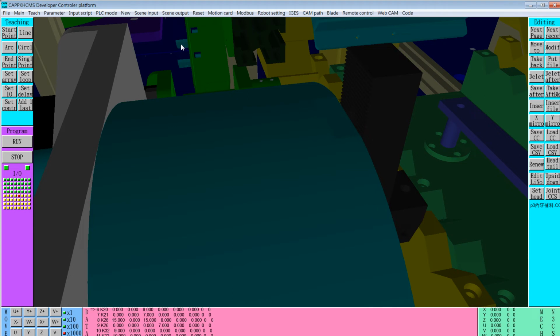And then this one in, the leading cylinder thrusts in, and the cutting cylinder retracts back to fit the parts in between here, and waiting for 5 seconds. The leading cylinder will retract back. Okay, let's run.